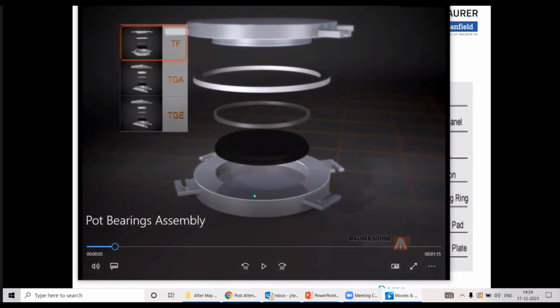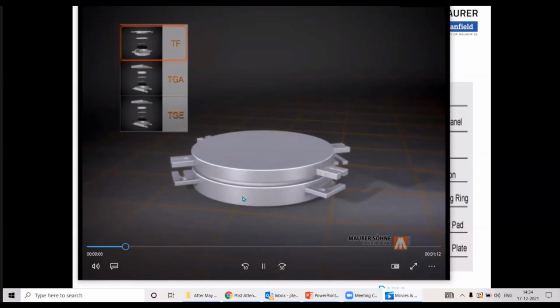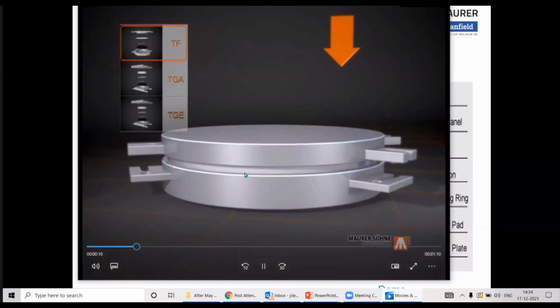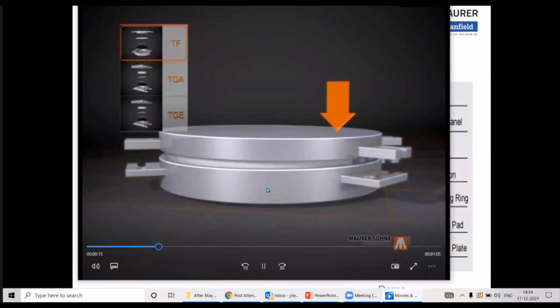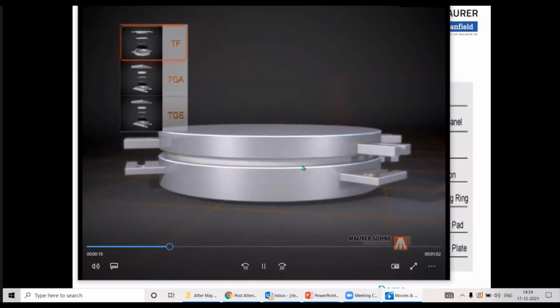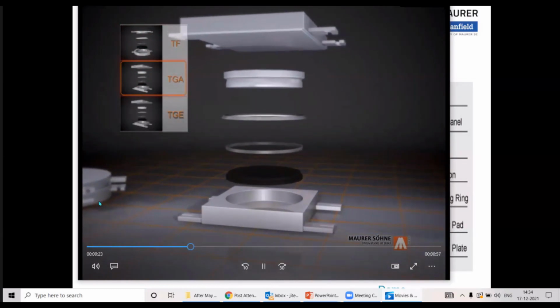Yeah. So we have this steel cylinder at the bottom and the disc of elastomer which sits inside the cylinder. And there are some sealing rings which lock this elastomer disc inside the steel cylinder, and it is covered on top by another steel component called the piston. So in this assembly, once the elastomer is sealed inside the two steel components, it acts as a fluid under pressure. And when the bearing is provided with some eccentric loading or it is to take a rotation, the elastomer very easily tilts and it offers that rotation. That was a fixed type.